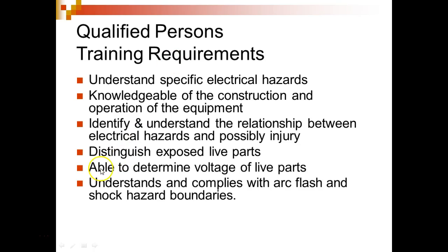This is a big problem that we have with people using test equipment to see what's there, instead of using test equipment to verify what's there, right? So what they're saying is that before you put a meter in a circuit, you need to know what you expect to see. And if you know what to expect to see, then you know if you got a meter that's rated 1,000 volts and you're going to try to measure 2,300 volts, you better not put the meter in there.